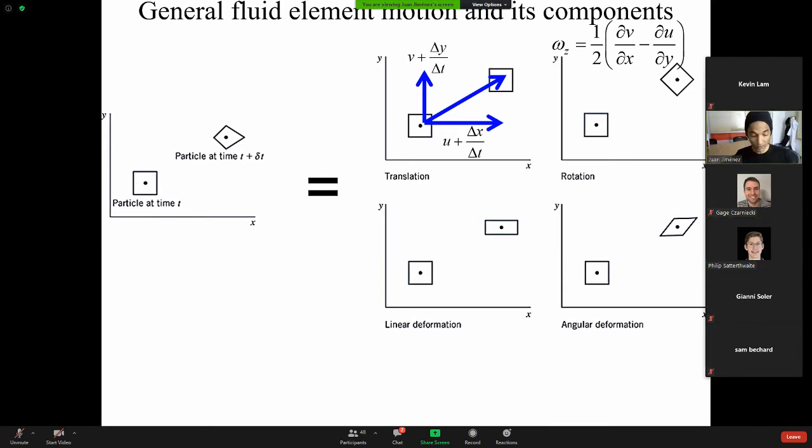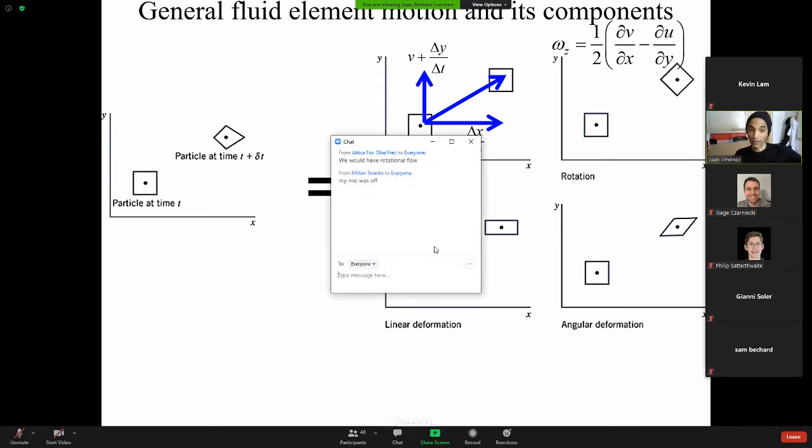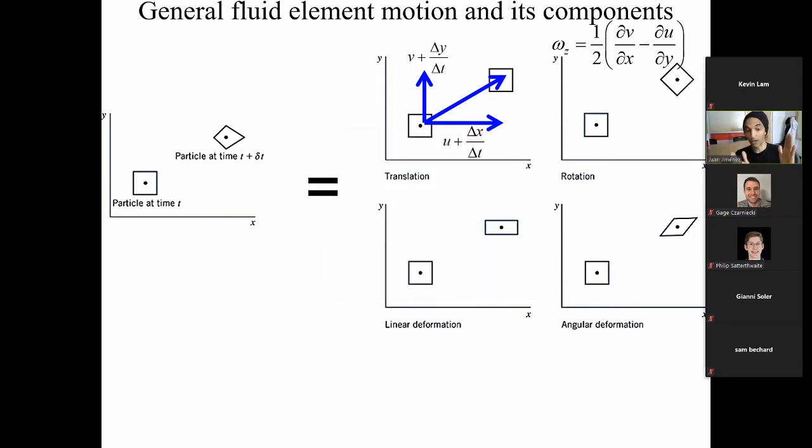Okay. So everyone, please make sure you understand that if you have a velocity gradient, the flow is going to be rotational. If you're at the beginning of the flow in the pipe and it's uniform, where all your vectors are the same length regardless of position, you have irrotational flow. But if you're in a boundary layer or the flow has become fully developed where you have a velocity profile, the flow is rotational.